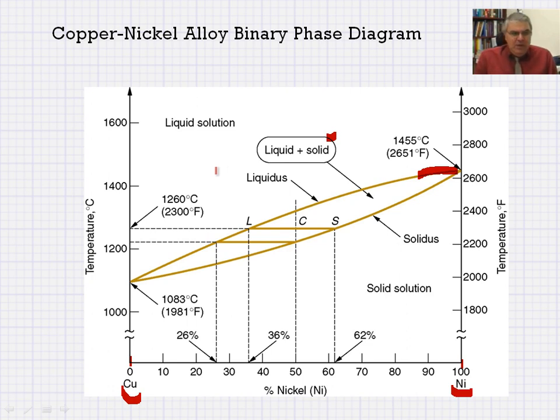That means as we are increasing the temperature, we are going to make the alloy a liquid solution. Under this temperature, as I show under this line, the alloy is solid. And there's some phase in between, between this line and this line, as shown on this graph. Well, they're not really straight lines, but between these two curves that show the liquid and solid states.